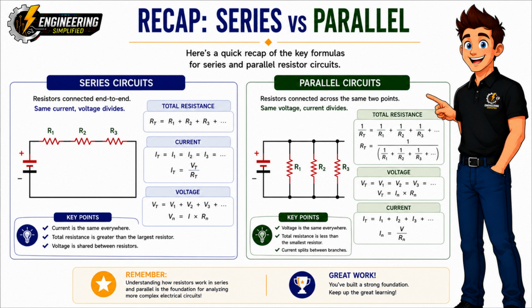So remember these 4 key differences. Series circuits: current stays the same, voltage divides. Parallel circuits: voltage stays the same, current divides. If you can remember those 4 rules, you'll be able to solve the vast majority of resistor circuit problems with confidence. In the next section, we'll combine everything we've learned and start solving mixed series and parallel circuits, just like the ones you'll see in real engineering applications.